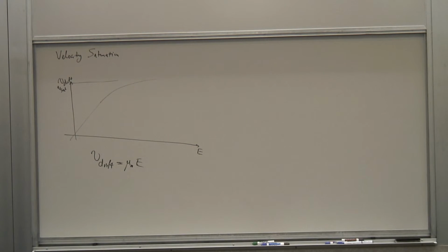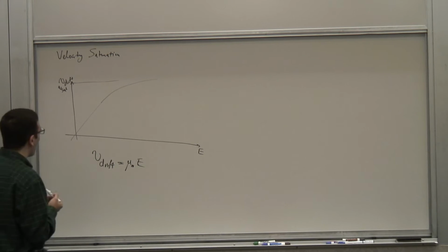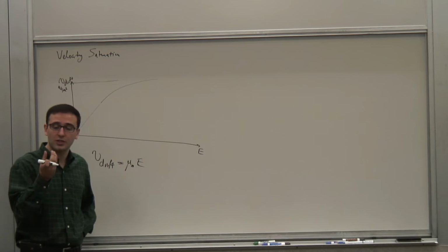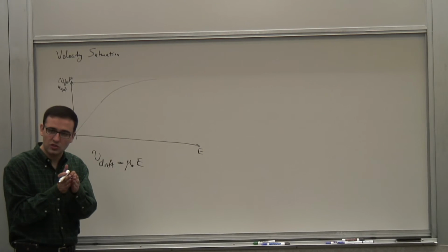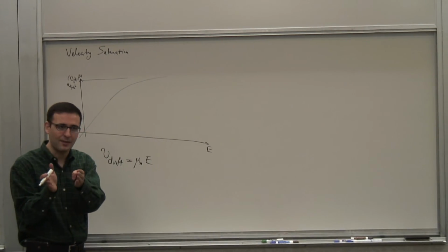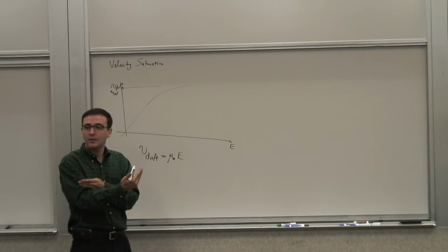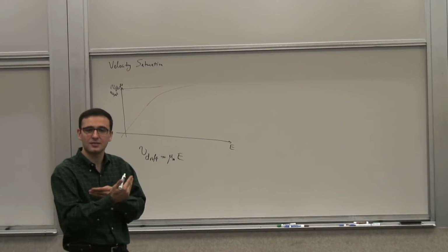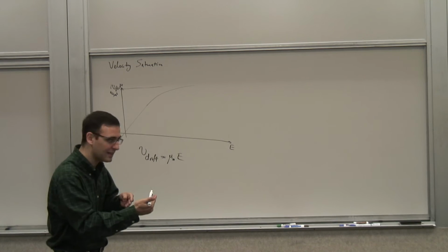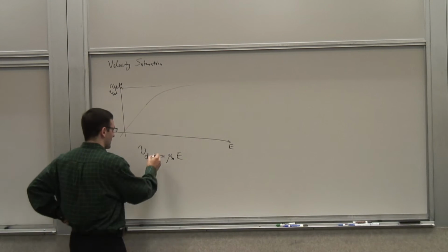Not in that form. Of course, not for the shortest channel transistors, but you know that the channel length L is a design parameter, so you can actually play with that and make a larger transistor. That's fine, but that won't be the fastest transistor. So for the fastest transistors that you can make in a process, you have a problem with this.